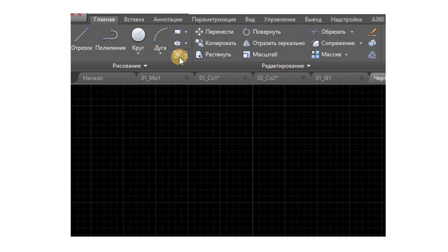Moving, copying, and stretching are for many drafters the three most common editing operations. AutoCAD obliges this need with the Move, Copy, and Stretch commands. The Move, Copy, and Stretch commands all require that you specify how far and in what direction you want objects to be moved, copied, or stretched.